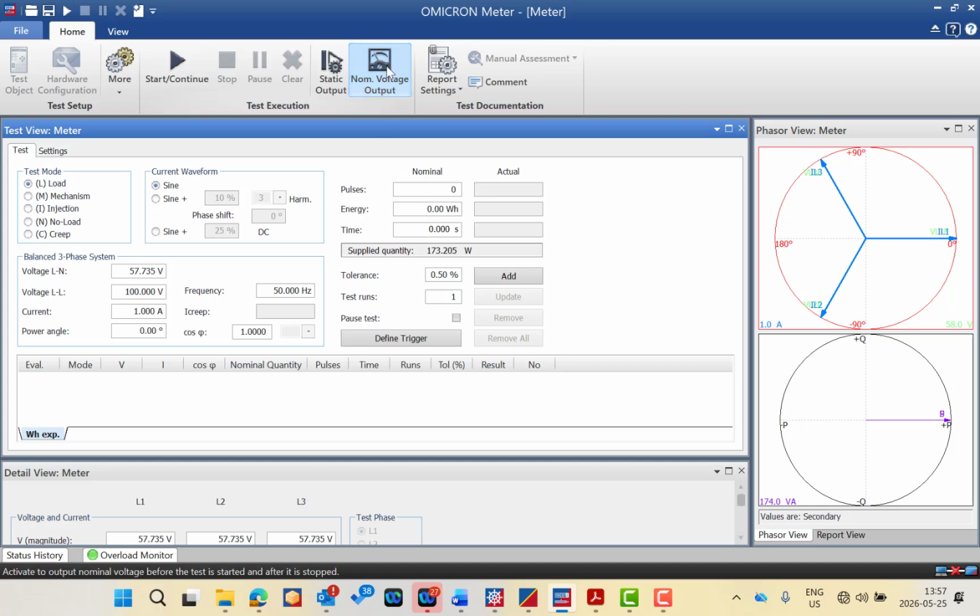When this option is enabled, the nominal voltage is applied directly to the analog output of the CMC. If several test points are executed one after another, the voltage remains continuously active until the test table sends another control command that changes the output conditions.